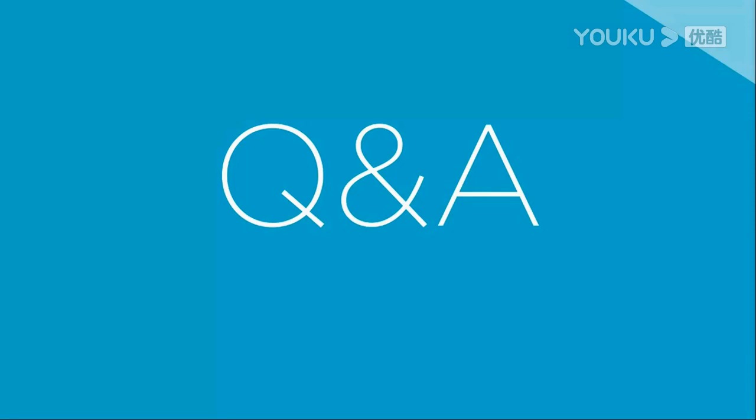Then we have a question: will nRF53 or nRF52 be able to support simultaneously LE audio and native BLE for data transfer? I'm not 100% sure on this, but I'm pretty sure that we will be able to do concurrent LE audio and BLE data transfer. But you only have one radio with a finite radio time, so this needs to be managed somehow, so that you have enough throughput for your audio transfer.